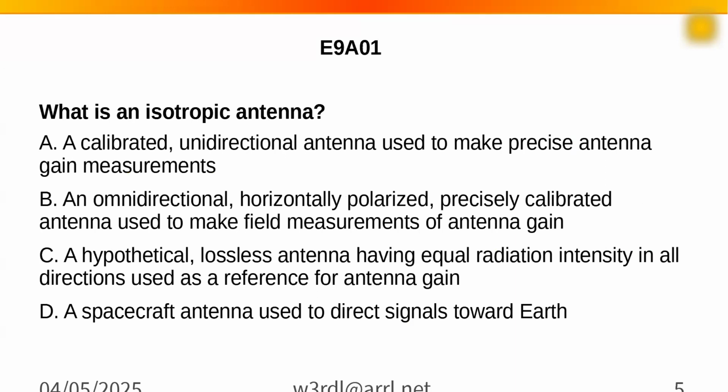Okay. And a dipole is 2.15 dBi. They always say it was 3, but it's really 2.15 in theory. But ideal, yeah, since you can't make an isotropic, it's theoretical. So it's all smoke and mirrors anyway.